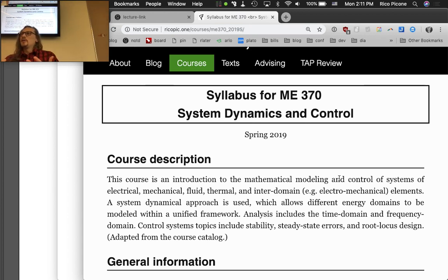If you're interested in that, you would need to go to a more detailed heat transfer perspective, and really probably a finite element perspective. And what we're doing here can be transformed into that kind of thing, where you take smaller and smaller lumped parameter elements, where you, instead of having one for a body, you could have 10,000 for a body, and then just take like little voxels, they're called, so volumetric pixels, that are describing each little bit of the body.